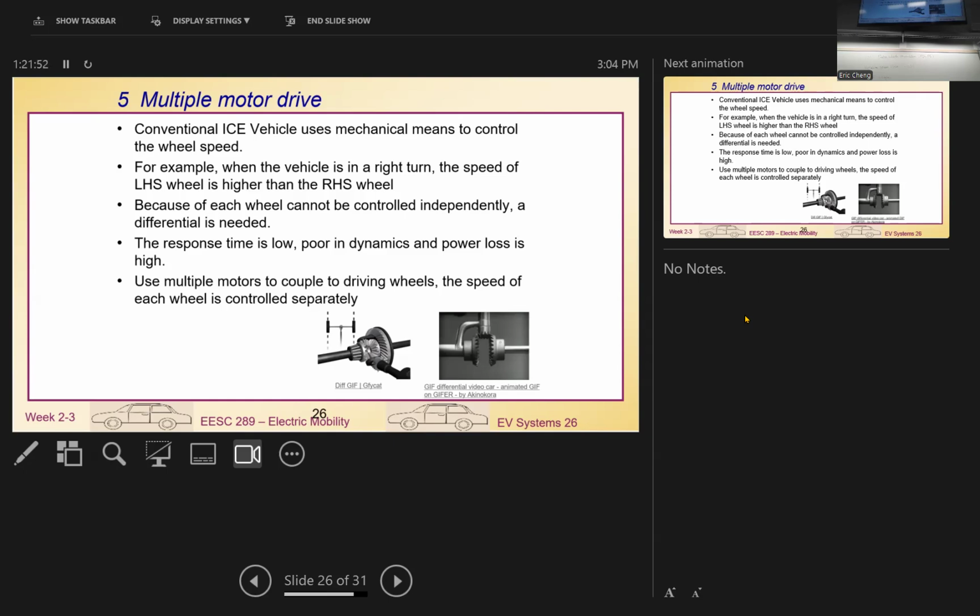At the moment, once hit, the wheel becomes locked. We need to use 20 hertz, 15 to 25 hertz, to unlock the wheel. That is not only the motor now, there's an additional braking motor to do the job. In the past, we only used hydraulics to do that, but hydraulic response is too slow, not able to do everything. We cannot control each of the wheels to that individual performance.